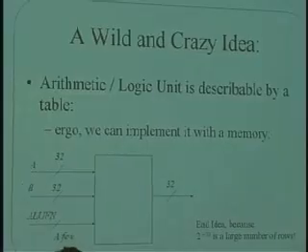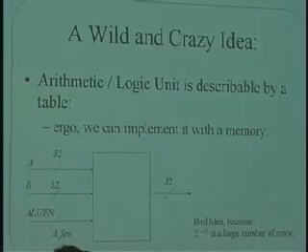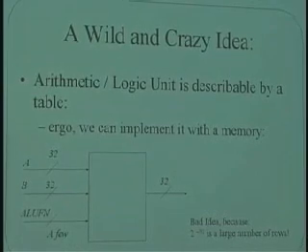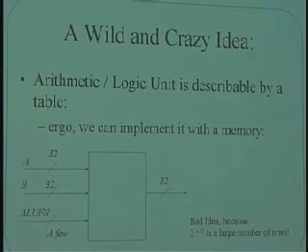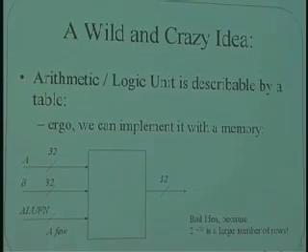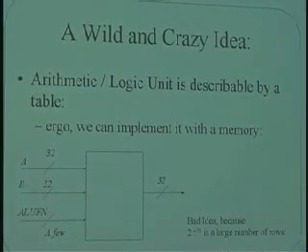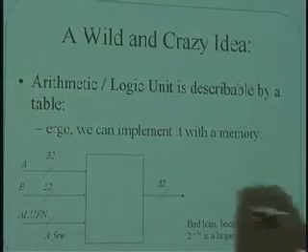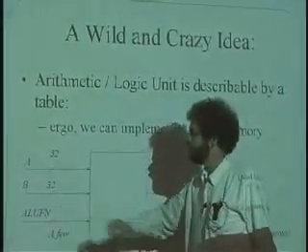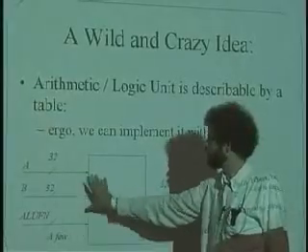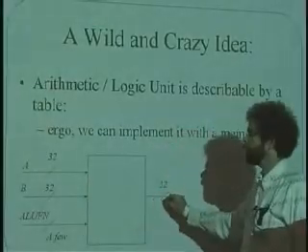This isn't hard to do at all. In fact, for every 32-bit number A, and every 32-bit number B, and every ALU function, which is going to take a couple bits. Like, how many bits could it take to do add, subtract, and, or, XOR, all those things? Let's say, I don't know, 5 bits, okay? So there's 32 bits here, and 32 bits here, and let's say 5 bits here, for a total of 64 plus 5 is 69 bits that go into here, and 32 bits out.